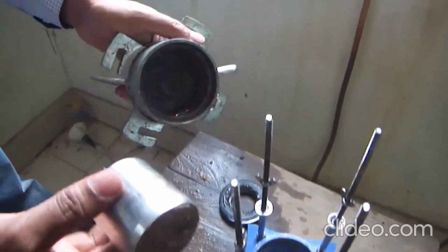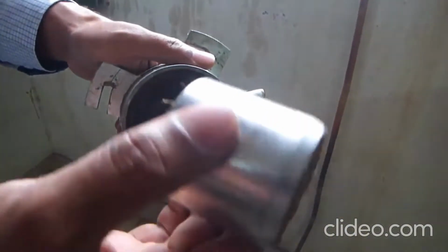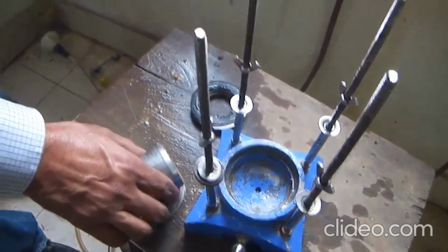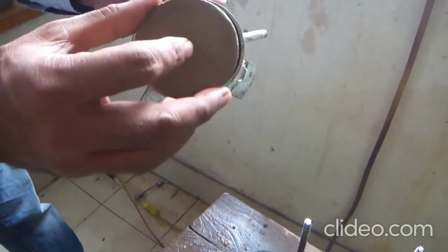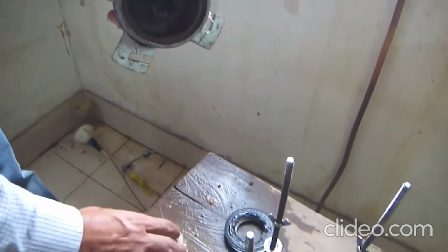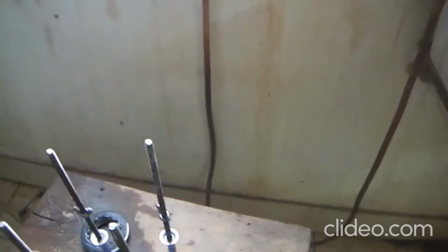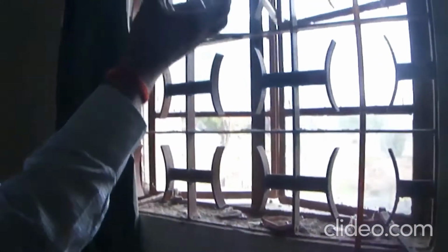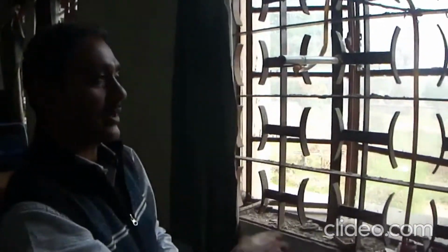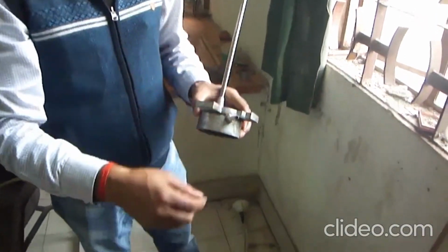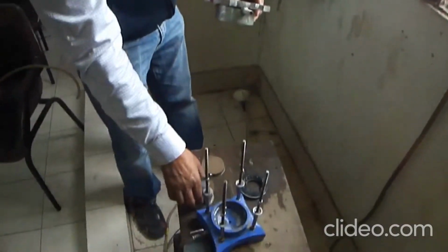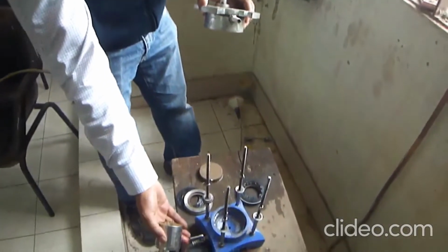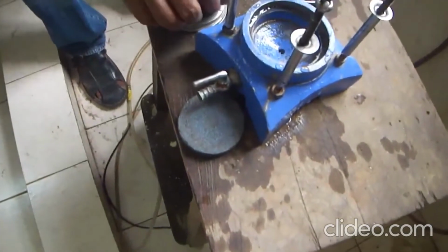How to maintain the constant head? This is a simple setting where we put this sample inside a cylinder, with two sand plates, supplying water or allowing water to go inside this sample, and it is also maintained at a constant head from the tap to what is called the source here, or we can say sump, from where water is going constantly to this sample, and the output of water that is going through this soil is collected at the bottom. So let me show you how it is arranged overall.